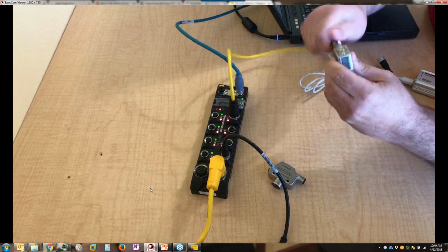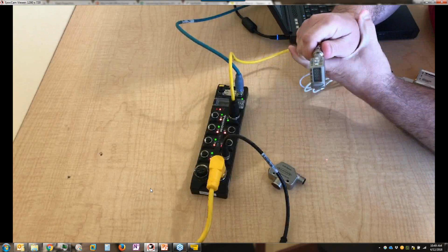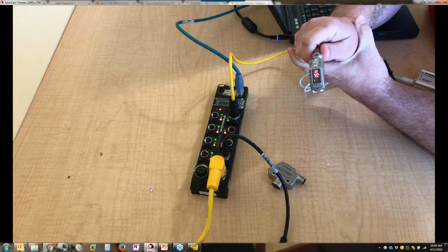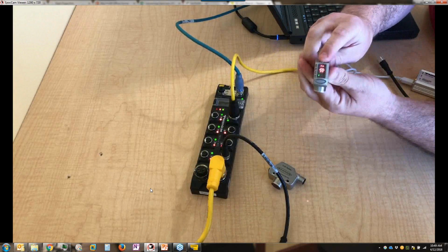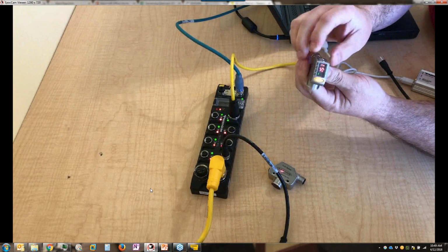If I remember, this has also been set to factory default for 150 millimeters. Okay, so on the front of the sensor, I'm going to teach it. I'm just going to hit the plus button here.